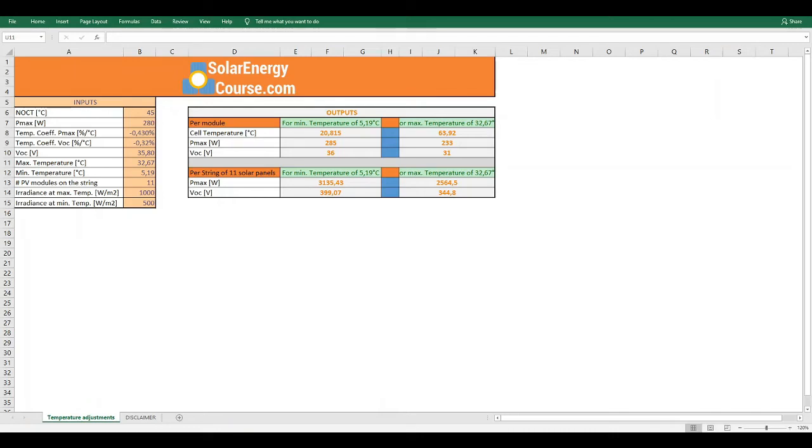Hey everyone, thank you for watching this video that is complementary to our solar energy course from Udemy or our website. The idea of this video is to see how to use the maximum and minimum power and open circuit voltage of the PV modules and string of your system, adjusting the values by the minimum and maximum temperature of the region. As you know from our solar energy course, at low temperatures the PV modules have a higher voltage, and at high temperatures the PV modules have a lower voltage. And we need to make this adjustment when we are designing our PV system.